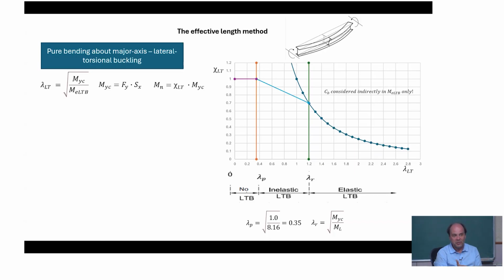Now, as this course is mainly about metal buildings, which typically have slender webs, and for slender webs, even in Design Guide 25, it was basically said that, first of all, the CB is typically not as beneficial as for a uniform section if it's calculated correctly. Second, this increase effect probably cannot be reached as efficiently as in the case of a hot-rolled beam because of deformations due to the shear. So the slender web will suffer deformations, and ultimately it will not be able to reach as high a strength as it could without such deformation under the stress gradient.